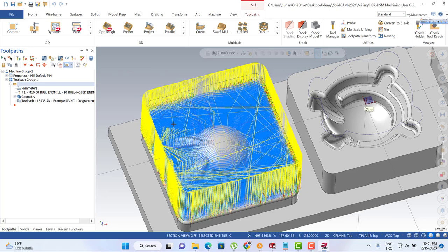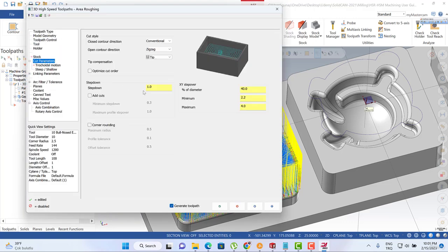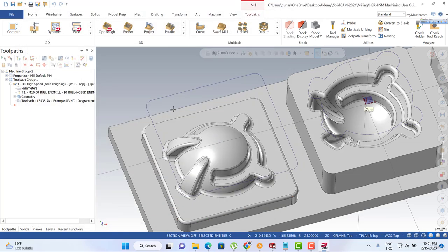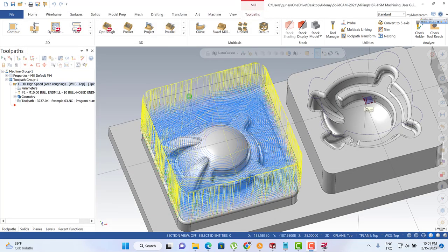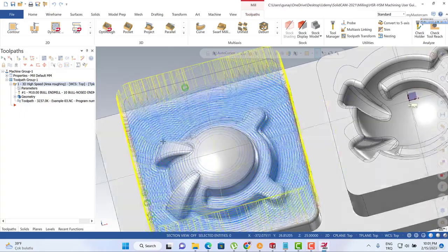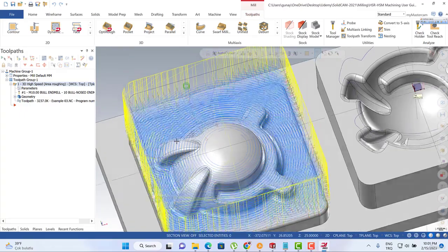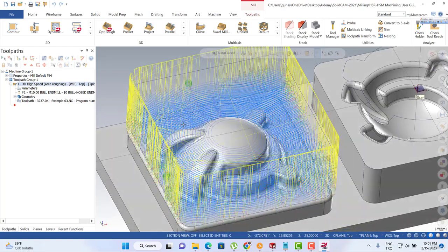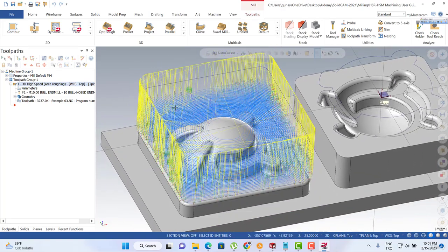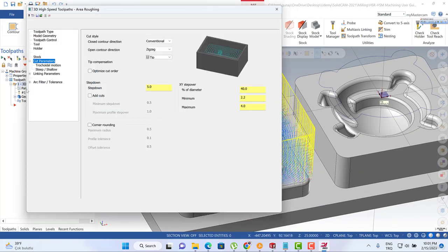To be able to understand our process, maybe it will be better for us to change our cut parameters. I should make them 5 millimeter. And then we're gonna see that kind of toolpath. Okay, so we can see the G0 movement here.